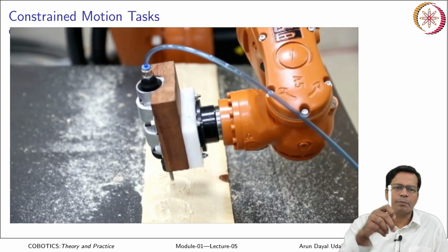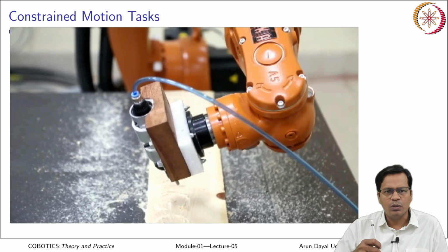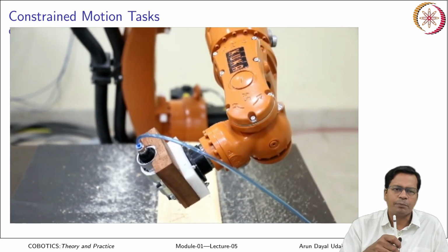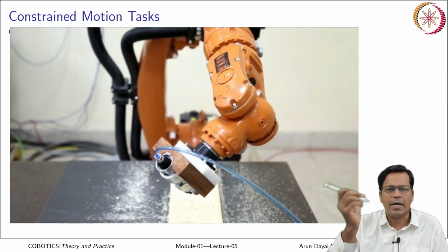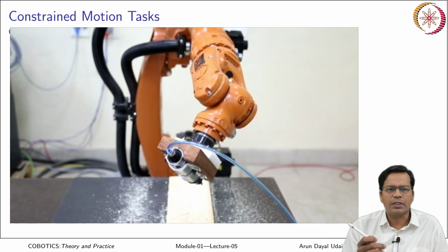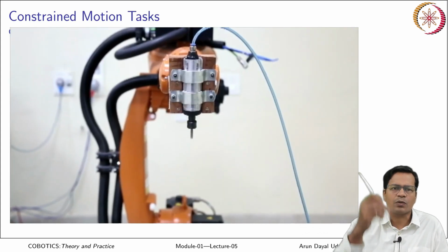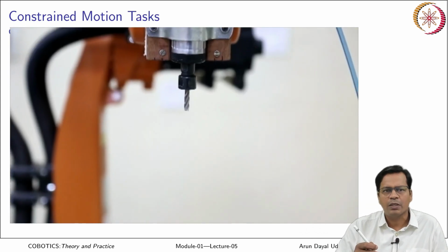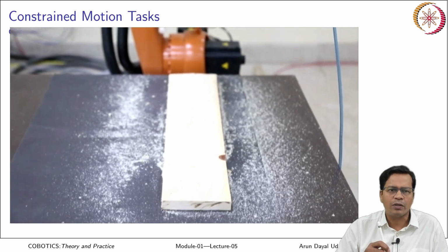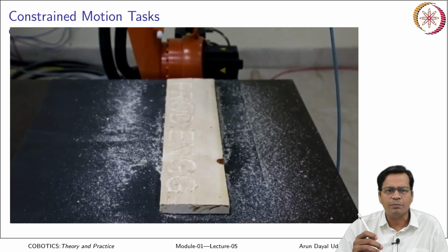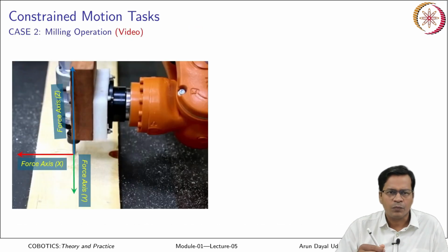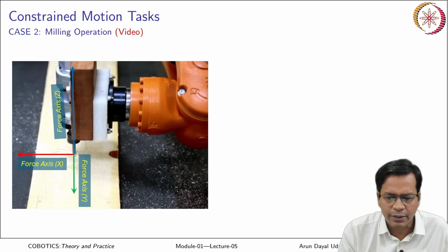So, once it is completed, it takes up the tool. Okay. So, reaching till that point and going back is basically a position control task. So, it is a position control trajectory using a standard robot, but maintaining the contact, doing this work requires some compliance in action. So, that is what is realized here.